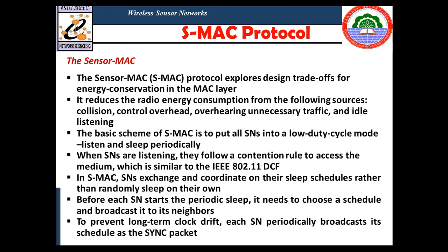In general, SMACS is an infrastructure building protocol that forms a flat topology for these sensor networks. SMACS is a distributed protocol which enables a collection of sensor nodes to discover their neighbors and establish transmission as well as reception schedules for communicating with them, without the need of any local or global master nodes.